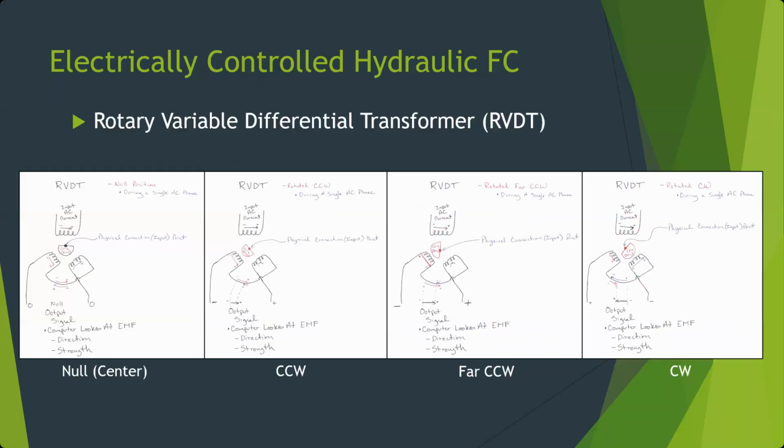If one of these fails, they don't get any kind of a signal. They basically lose output, or they get weird signals. And so typically these are done, not only are they more reliable, but typically we have at least 2 of them providing input signal and 2 of them providing position monitoring on the output side when they're used in something critical like a fly-by-wire system, a flight control system, or even our nose wheel steering on the aircraft that had these. There were 2 of them in the tiller, and there were 2 of them down on the actual hydraulic actuators that turn the nose wheels left and right.